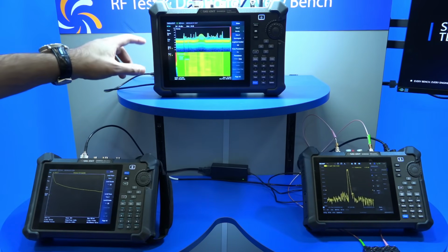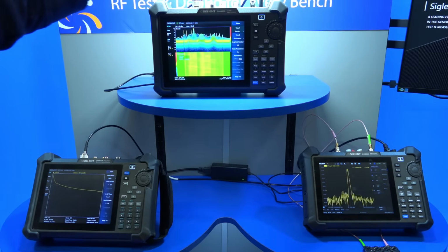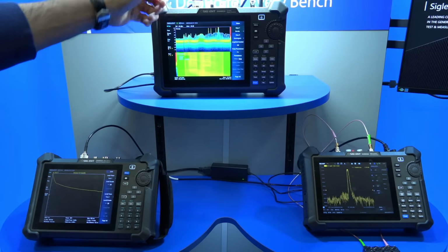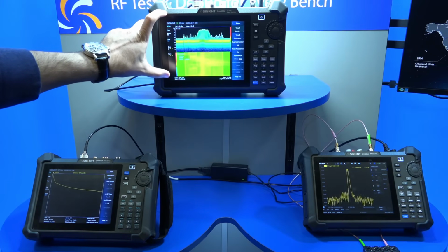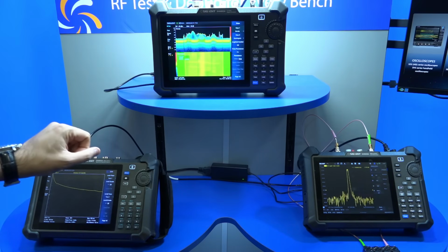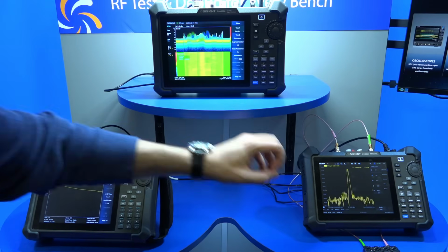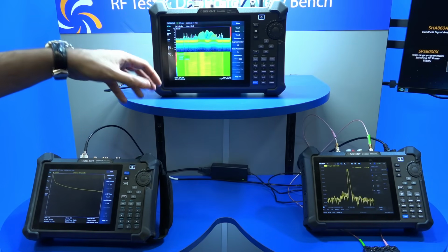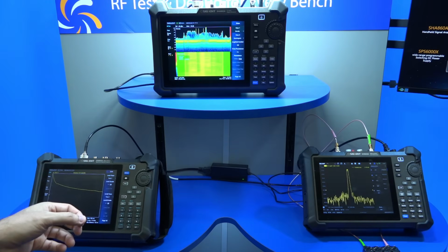And then they have their new 7.5 gigahertz real-time spectrum analyzers that have a 1-port, or one-way, S parameters. You can measure S11 and S21 in vector, but it does have 110 megahertz of real-time analysis with about 3.5 microsecond of 100% probability of intercept. So it's interesting that the network analyzer with spectrum functions and the spectrum analyzer with network analyzer functions give you an opportunity to pick which feature you really want to focus on.